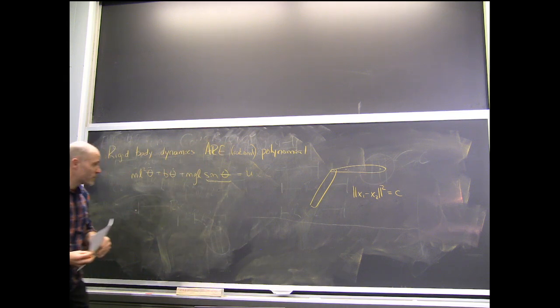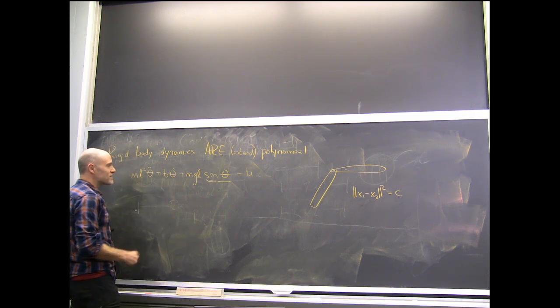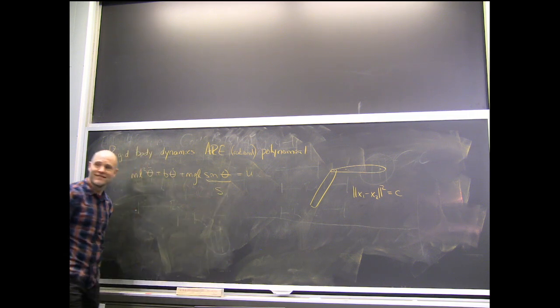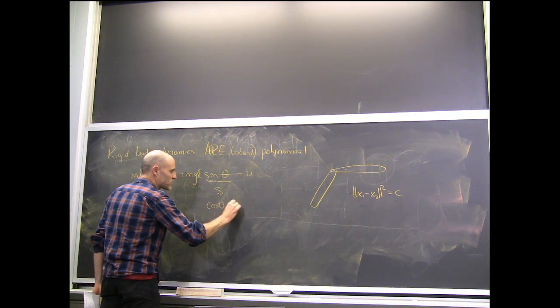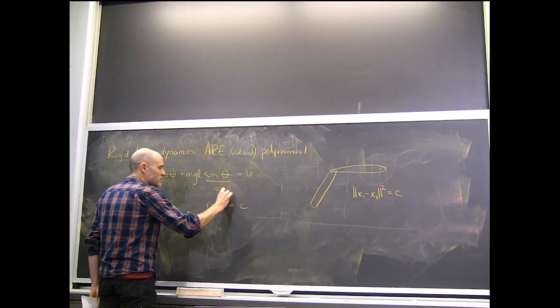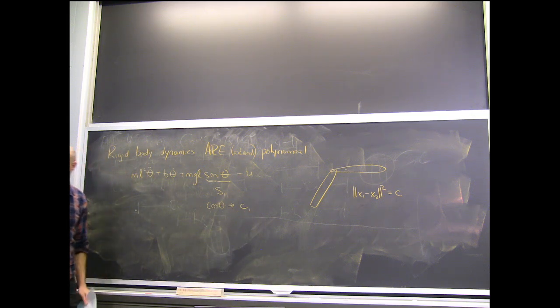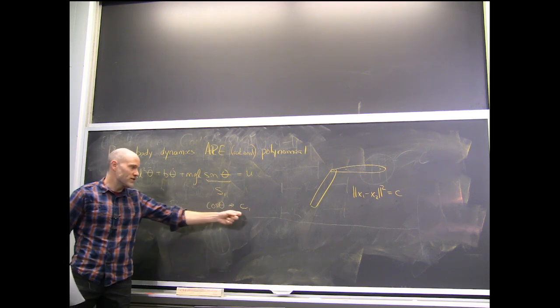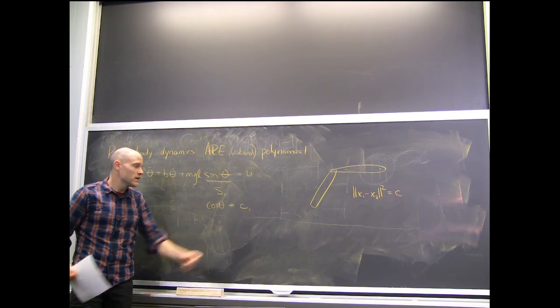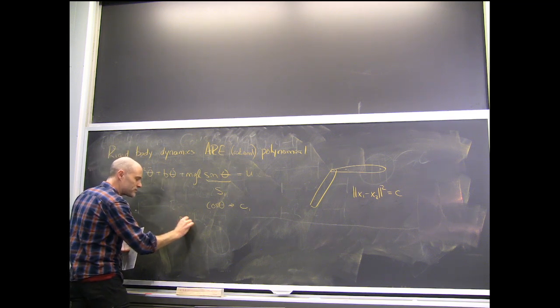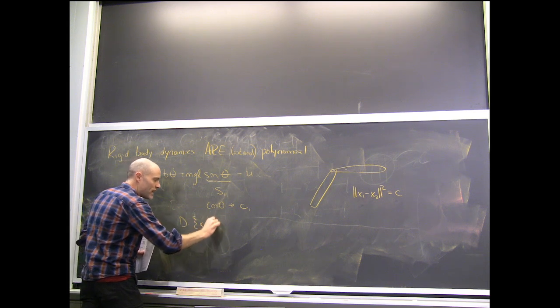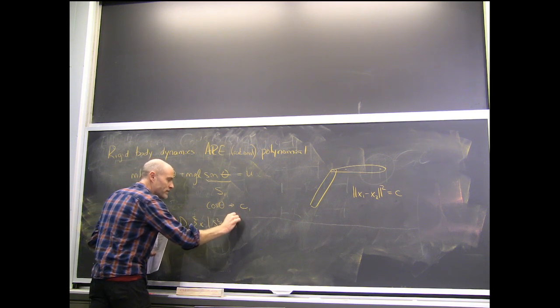And the simplest way to expose it is I'm going to just go through all my functions. Every time I see a sine, I'm just going to call that s. Every time I see a cosine theta, I'm just going to turn that into a c. I've got theta 1, I'll make s1, c1, like this. And my claim is that the equations will be polynomial in s1 and c1. And I want to live on a domain where s squared plus c squared equals 1.